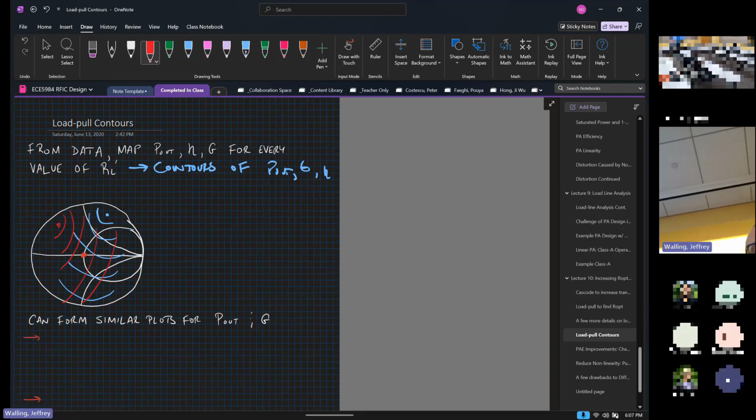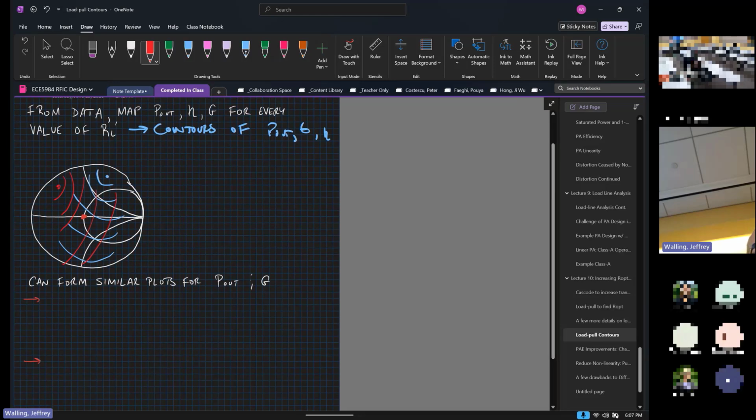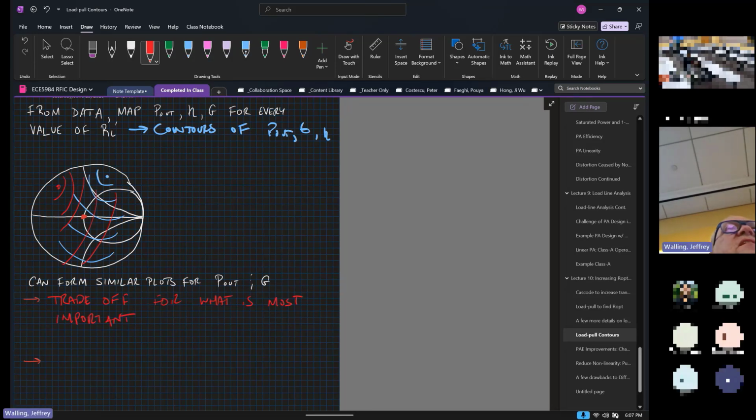Okay. So the biggest thing, in terms of how do I know when my design's done, okay, let's think at a high level engineering thought here. What is the benefit of having more output power from a system in a radio system? Yeah, I close the link at a longer distance. PTX goes up, and so my power available at a receiving antenna is going to increase proportionally.